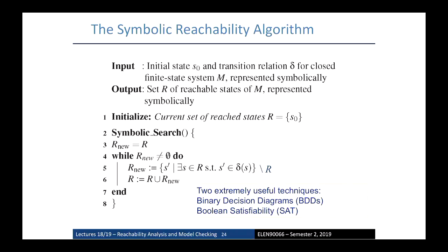Sometimes you can switch between the two. So you could try doing BDD to build up this set. You find out it's becoming infeasible, too complex or something, so you could switch to something like SAT as well, or start again with SAT. So it's a tricky problem. It's known as an NP-complete problem, to be able to find the entire reachable set of states of an FSM.